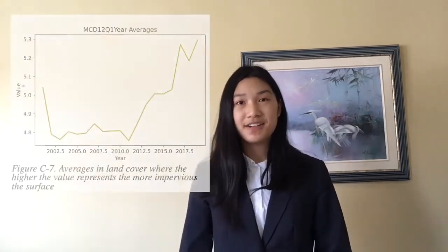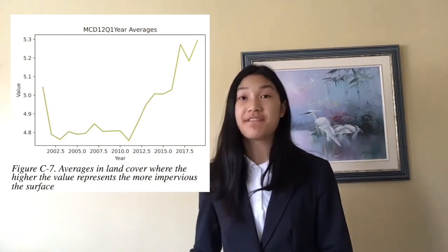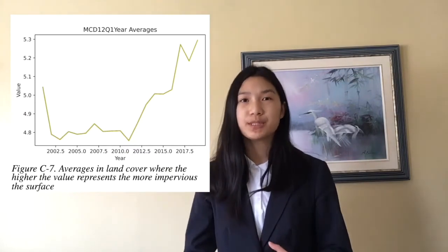And from the land cover, the average hydrologic condition of the area of interest was noted to experience a prominent increase. Intriguingly, the inundation probability of the area of interest enters a phase transition in 2016, reaching peak probability of the study duration only by 2017. This is likely a consequence of increased urban development, where activities such as replacing vegetated ground with pavement largely increase the imperviousness of the land.